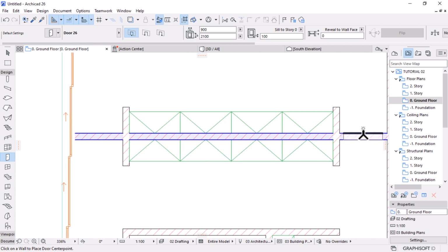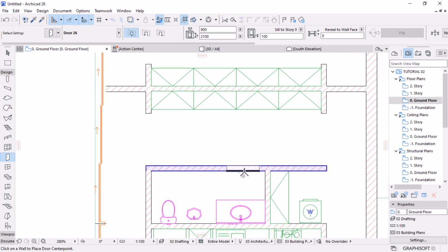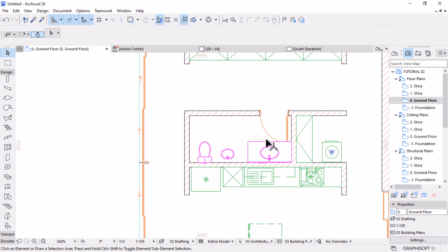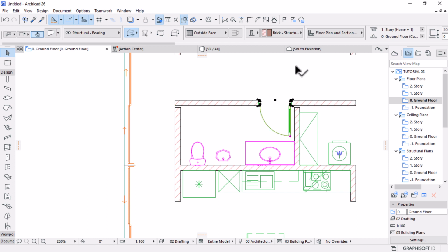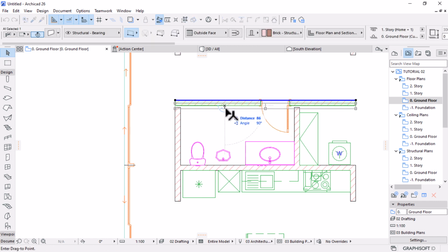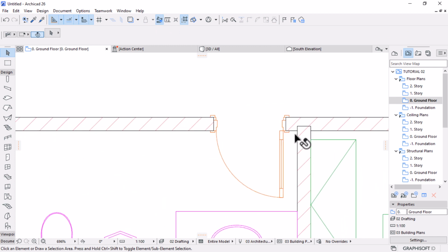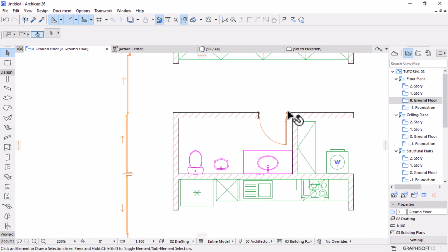Let's apply it here, and then oh sorry, this one goes by the bathroom, something like that. Okay, the space looks tight, it looks tight. We can maybe push this wall up by 200, and then I can also reduce the size of this door, which is 900 to 800, something like this. Let's move it back by 100. Okay, now I can pick these two line walls and intersect them. This I can do manually, stretch it across the width of that to snap and create a good joint.